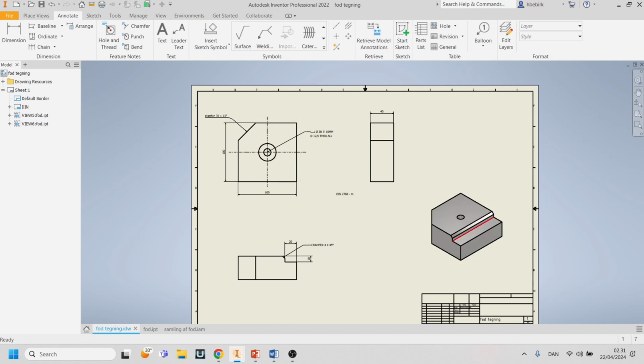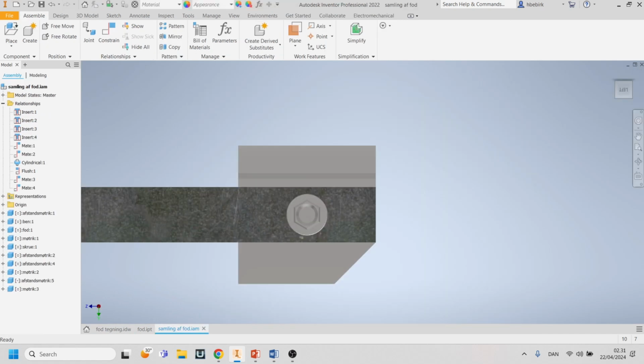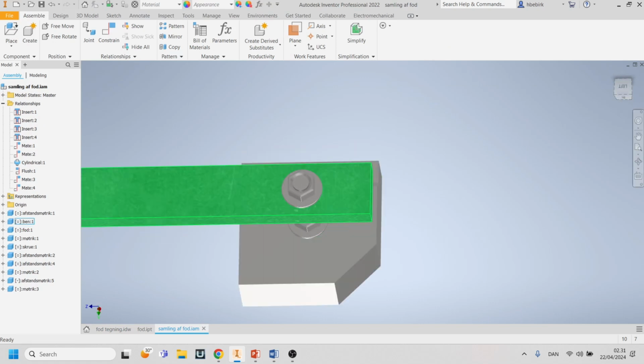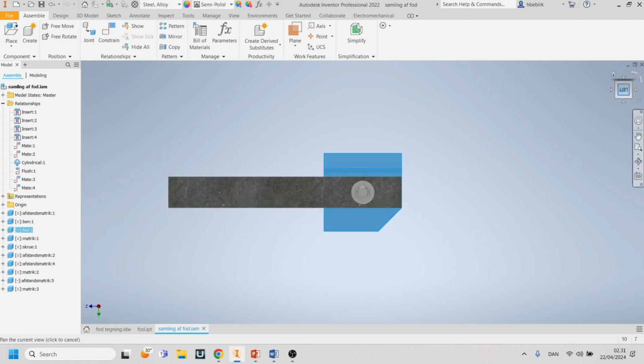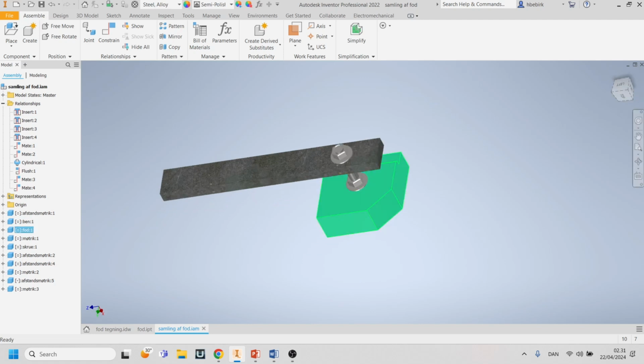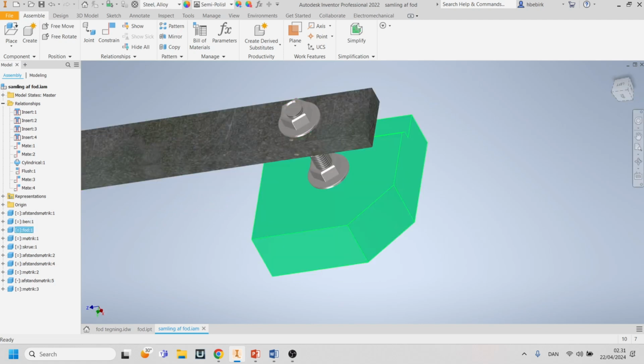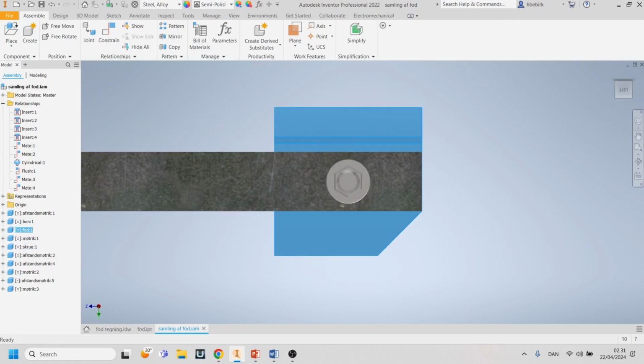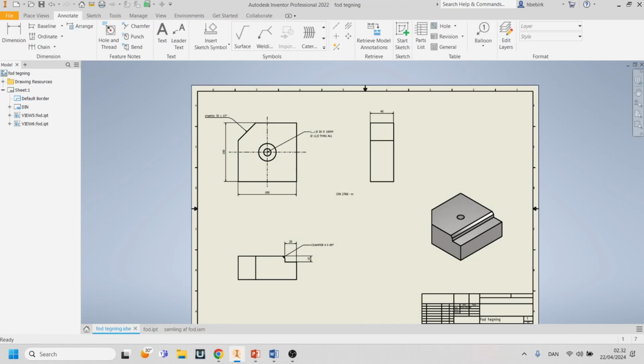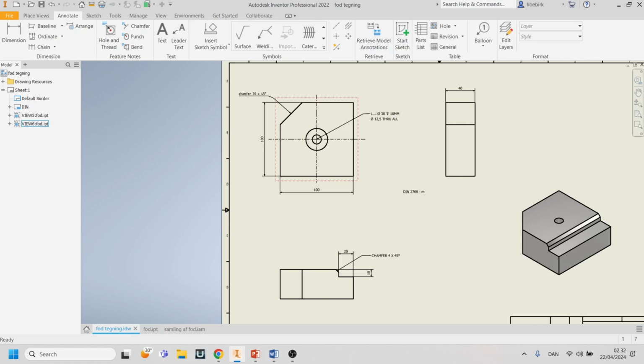And this way we can make sure that when we go to the assembly, the part does not exceed a high limit or a bad tolerance where this surface and this do not flush at all. Let's say this one was moved from the top view, these two surfaces from the flat bar and let's call it a feed, would be moved 1 millimeter or more, 5 millimeters. And this way we have now correctly talked about how it should be placed, the tolerances, and also what's important in this part to show the machinist what we want to be made.